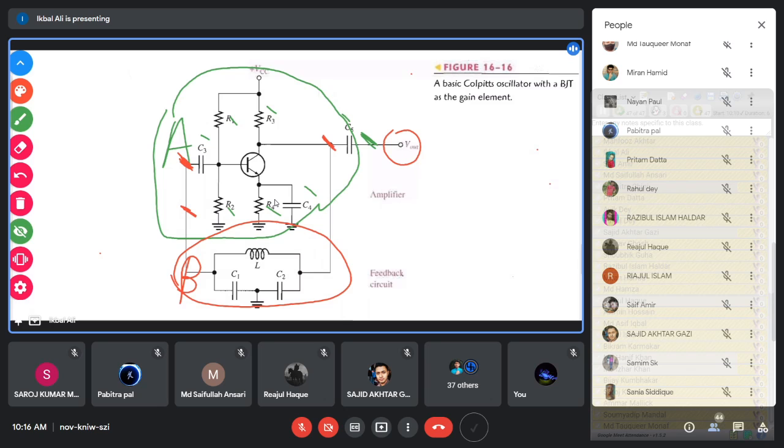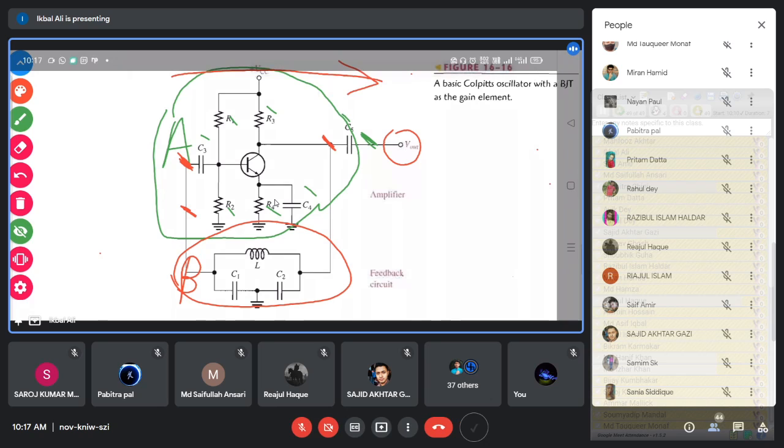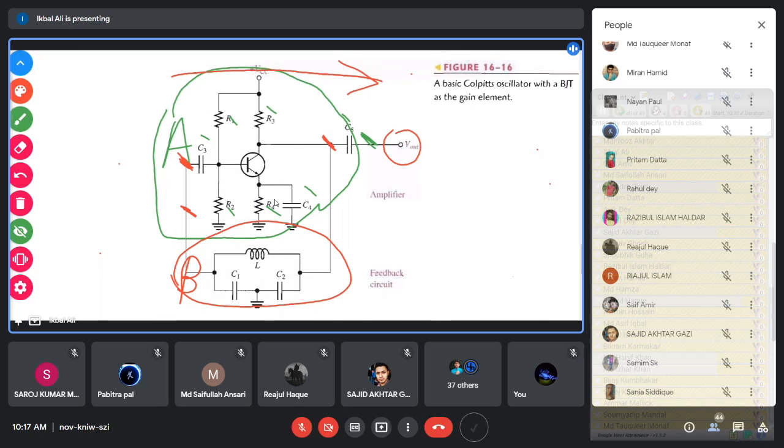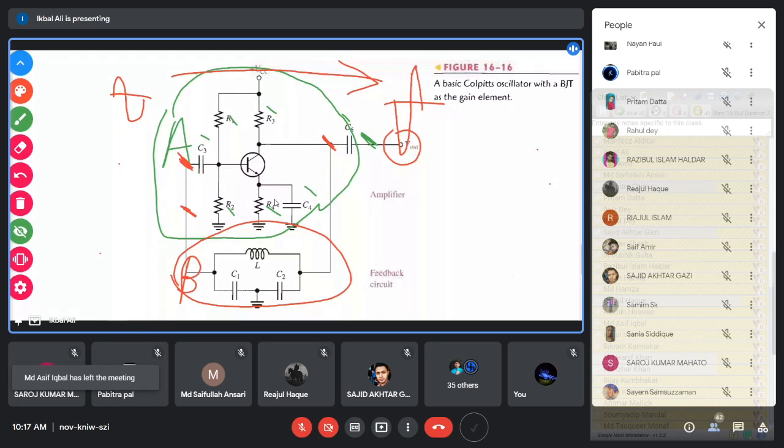So this is the construction, and we have discussed how the phase shift condition of the oscillator, that means the 360-degree condition around the A beta network loop, is satisfied. When the signal travels through the amplifier, a 180-degree phase shift will be there, because if the input signal at the input of the amplifier is like this, then the amplifier amplifies in the opposite fashion. So there is a 180-degree phase shift by the amplifier.